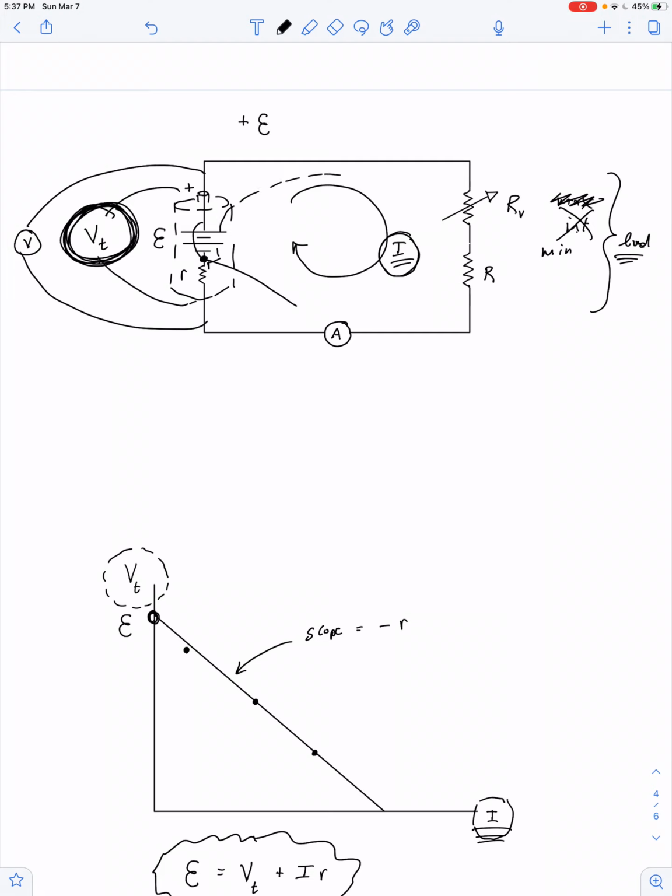We continue on until we get to our next circuit element. And we'll treat these two as being together as one, right? And we'll just say that the resistance of the load is this quantity, capital R. So now there's a loss in electric potential. And by Ohm's law, that's just equal to whatever the current happens to be multiplied by the total resistance of the load.